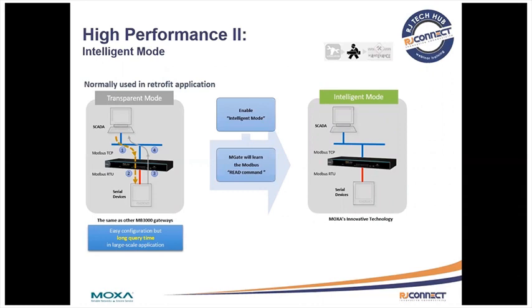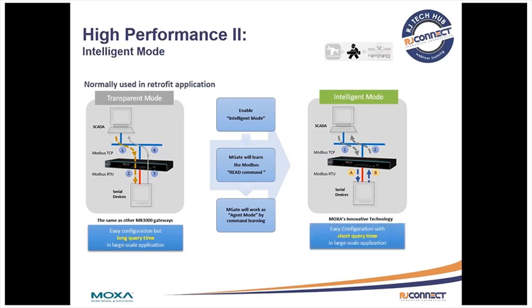So with intelligent mode, the Mgate will learn the Modbus commands from the SCADA, and it will work as an agent by using those commands that it learned. So it learns the commands from the SCADA system and then actively starts polling the serial devices using those commands. This makes it very easy to configure and shortens the query time in large-scale applications.